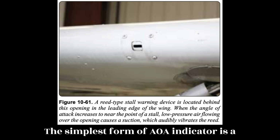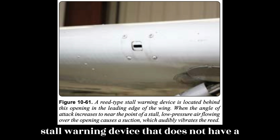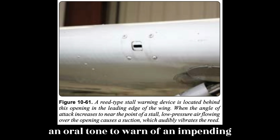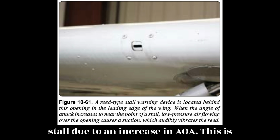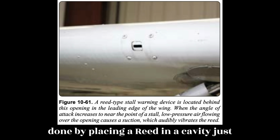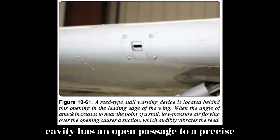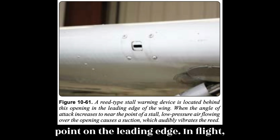The simplest form of AOA indicator is a stall warning device that does not have a gauge located in the flight deck. It uses an aural tone to warn of an impending stall due to an increase in AOA. This is done by placing a reed in a cavity just aft of the leading edge of the wing. The cavity has an open passage to a precise point on the leading edge.